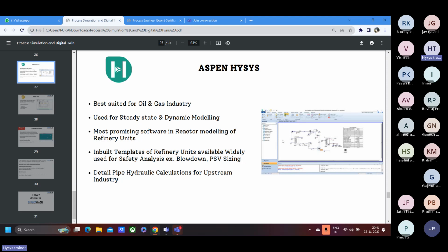By giving the proper property analysis, by giving the property state of art, state of equation, Peng Robinson or BWR, you will try to fine tune this model. After fine tuning it, you will put it into the other platform. From that OPC server, those kind of details are fetched by the model. It is run and it can generate this model into your another dashboard, which you can monitor.